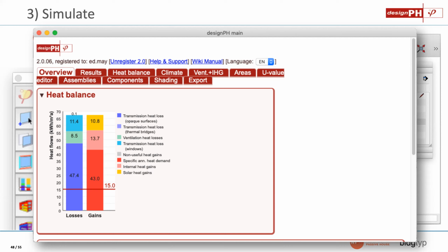What that means is that for a non-residential application, this preview is not going to give you that much information. It's useful, but only so far. It's not going to give you the full picture. The other real downside to this preview is that you don't see anything to do with cooling. Where I work in New York City, and in much of the US, we want to look at heating and cooling at the same time. And there are simply no cooling calculations done whatsoever in the preview. So in order to get any really useful information, you have to go to the PHPP.